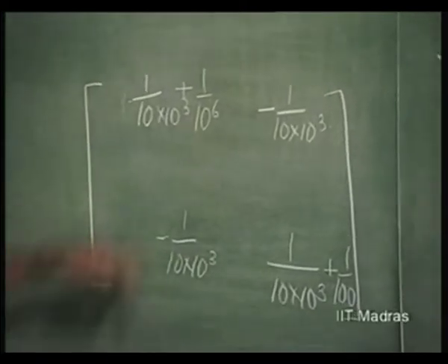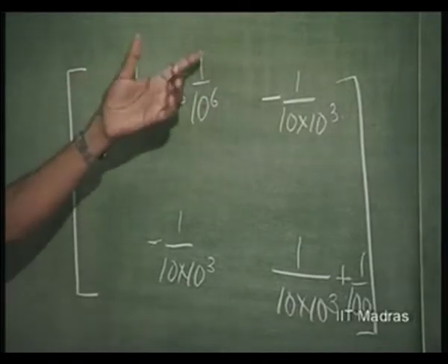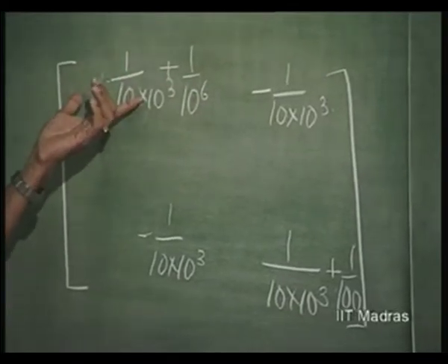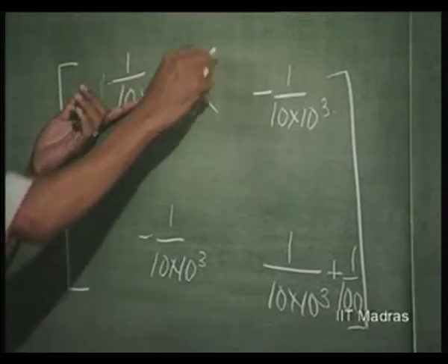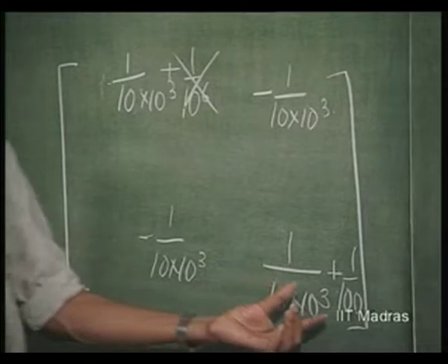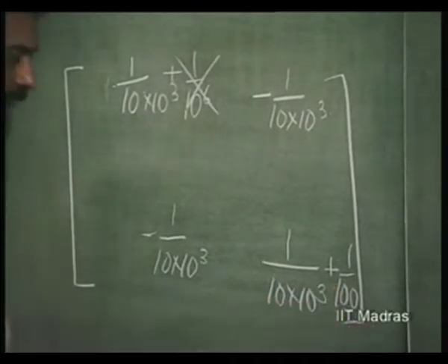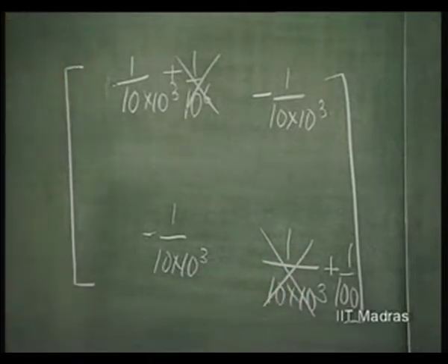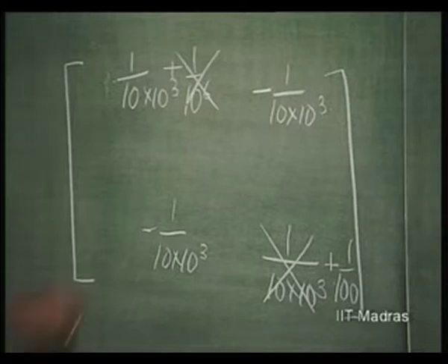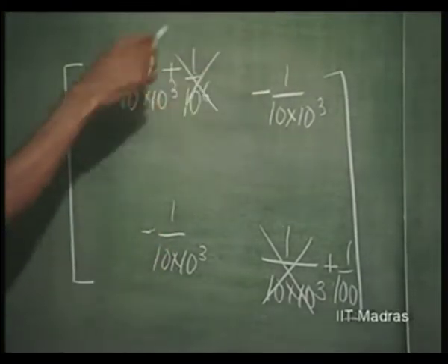So, you can see that at the input this has negligible effect on this, right. So, this can be ignored, right. At the output, RF has negligible effect on this. So, this can be ignored. As far as feedback is concerned, only the passive network contributes, active network does not contribute.